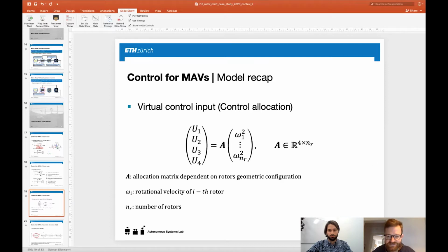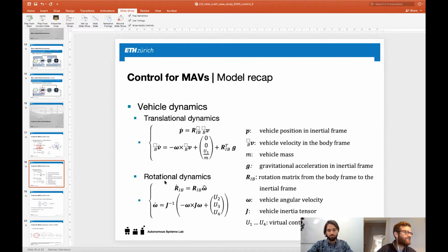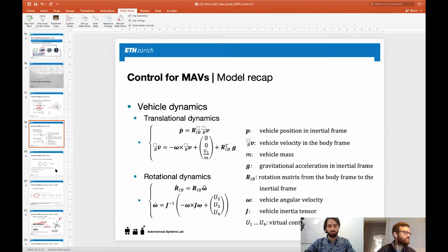Okay, we got another question, what the omega hat meant. Okay, wait, I don't know if this is written anywhere else, but basically we use omega, which is the angular velocity. So it's just like omega x, y, and z. And we use this hat operator to make the vector into a skew symmetric matrix. You can probably look this up online. I think it's not written anywhere here. Basically it makes a vector into a skew symmetric matrix.